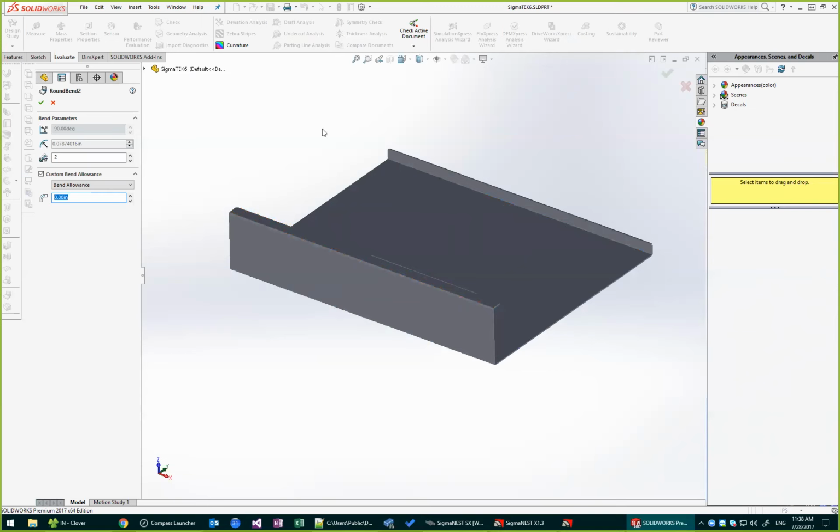So if this is not a sheet metal part, it'll do its best to unfold just the 3D body. But because this is sheet metal and because I have a flat pattern, it is assumed, since that was what was included with the part, that is what is intended to be manufactured. So it's just important to note that the unfolding bend parameters used for this sheet metal part in SolidWorks are maintained and correct with the other systems as well.